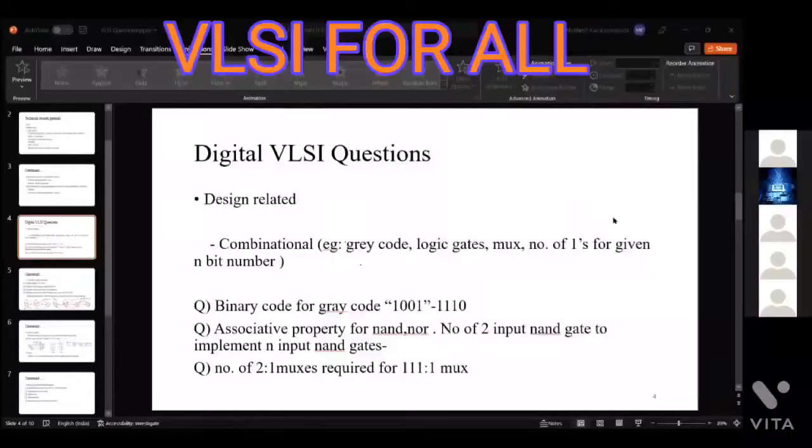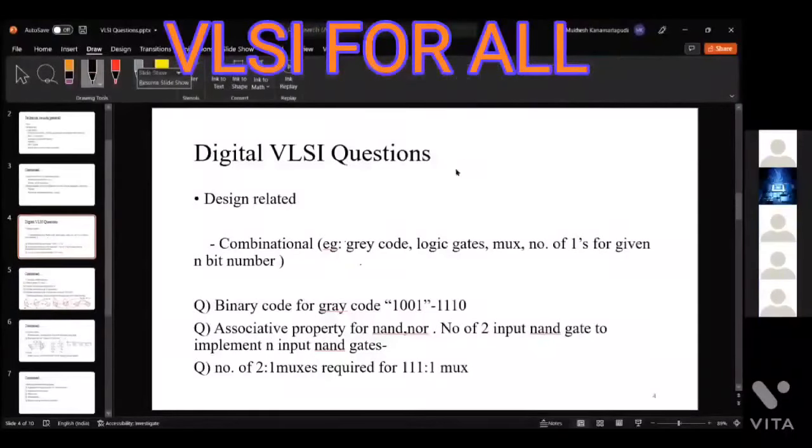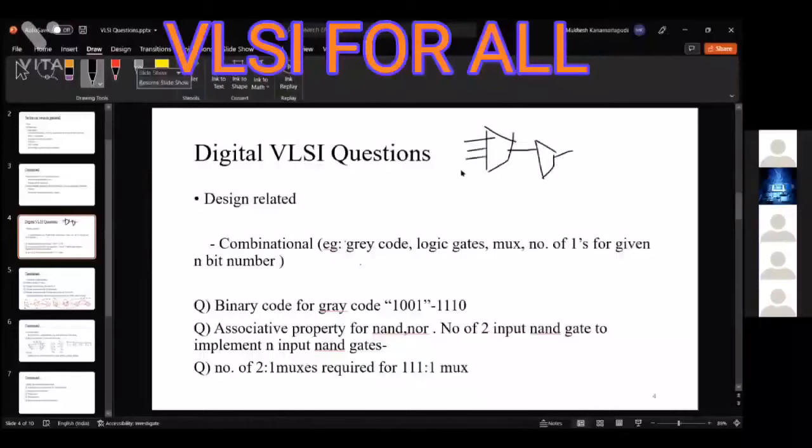Sir, in the second mux, the first mux output is given as input to the second 4:1 mux, right? Yes. But still, I can give 7 inputs if I'm designing like that, sir. So can you please check? Yeah, I'm writing. So here there are 4 input lines, and this last input will not be used, as you have said 6:1 mux using only 4:1. So this last input cannot be used. You cannot do anything regarding it.